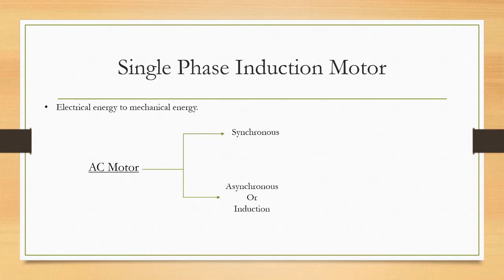In three phase induction motor, we are giving three phase supply to the stator. So due to that, a field is created that in turn creates a flux. This flux travels through the air gap and touches the rotor conductors. The conductors may be copper or aluminium or an alloy of copper or aluminium. Then an EMF is induced there. Because of that, a current is produced there, so that a field and flux are produced around the conductor.